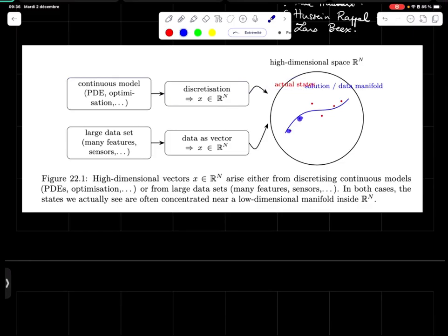So what does state mean? These are all the simulations that you make. And then you say, well, I'm not so interested in everything. I just would like to have a low-dimensional subspace that's going to go through these points, but it's not going to be exactly those points. Doesn't really matter. I just want something that is an approximation. And that approximation can be a simple line. And that's going to be what is called POD, or Principal Component Analysis, PCA, which everybody hears about because this is the favorite method of any data analyst.